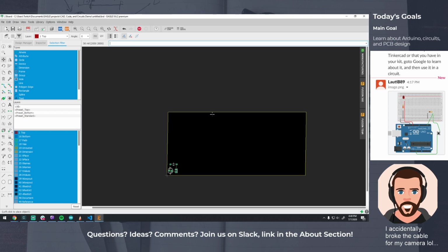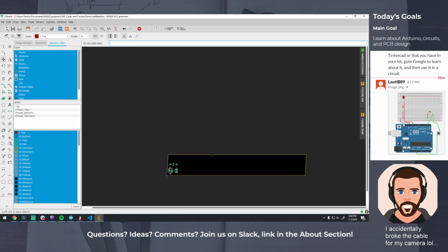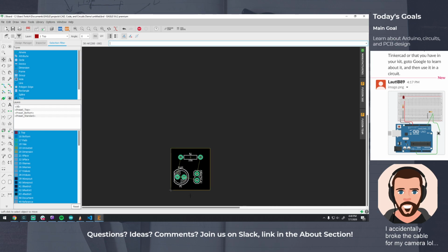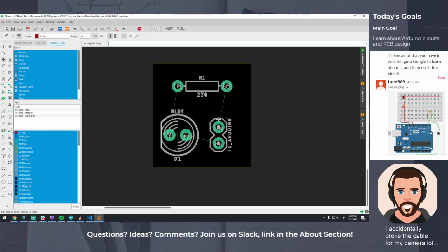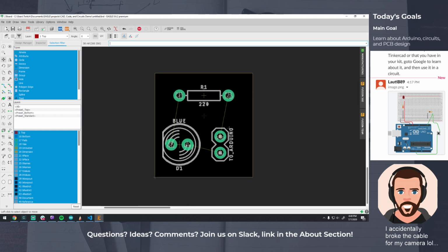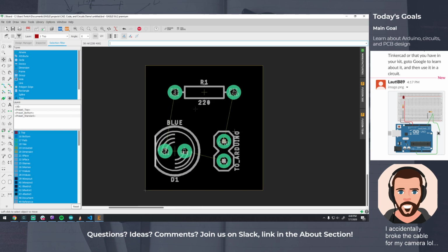So now we can click and drag these lines down. Be careful as you're dragging, you can kind of end up rotating them in weird ways, so just try and make sure that they're totally vertical and totally horizontal. Cool. So now we'll zoom in, so we can use the middle scroll wheel to zoom in, and if we click down, we can drag it about. So these aren't actually traces yet, these yellow bits. They will be traces, but we just have to say where the traces will go.